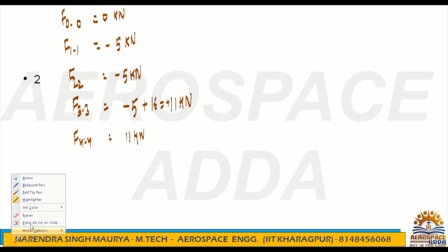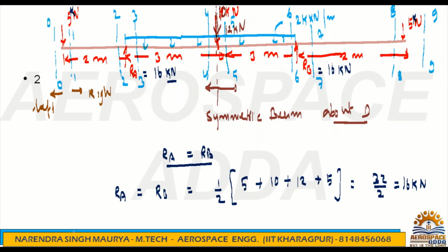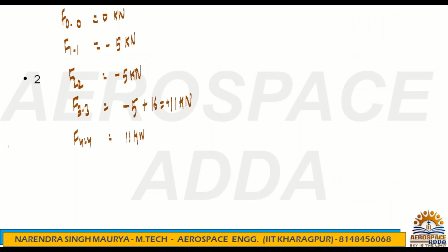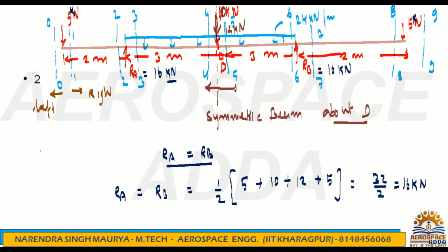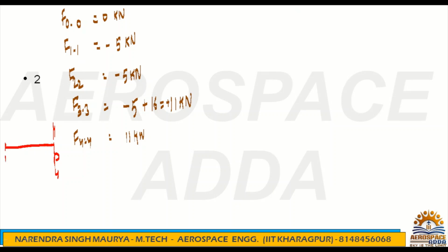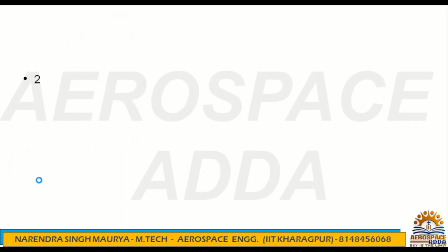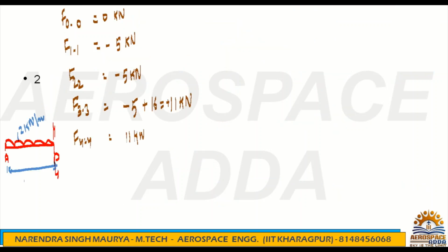This is very important. So for F44 I am showing you. F44 is exactly at D, just before D. So you can consider D. This is D where we are taking F44, right? And this is A. Here we have UDL. So I'm showing you how to calculate for UDL. This UDL is 2 kilonewton per meter. What is the distance between A to D? It's 3 meters.